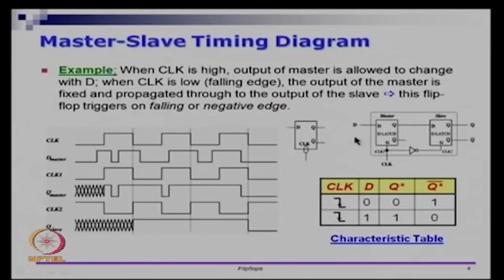You can now think about this whole circuit, this D flip flop, as a black box. What does the black box give you? Whenever CLK goes from 1 to 0, D will be sampled, and in all the other time periods Q will be retained.